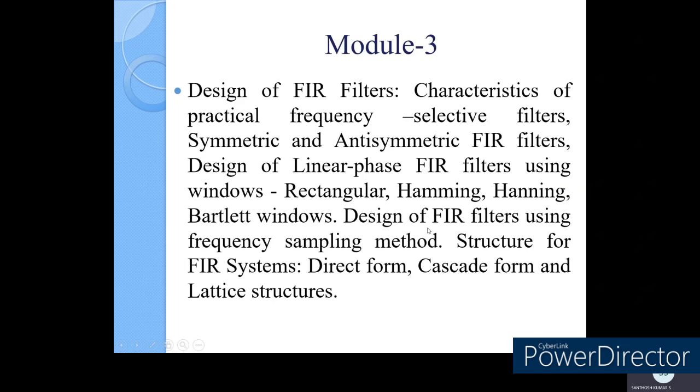So the frequency sampling technique is nothing but taking the Fourier transform of the impulse response. For that, you perform the sampling in the frequency domain, and for that sampled signal we take the inverse DFT, so that you get h(n). That is called the frequency sampling technique. We are going to use that method to design the FIR filters.